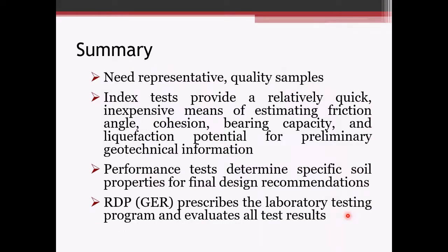So to summarize, we want to make sure we get representative quality samples from the field to the laboratory. Index tests provide a relatively quick, inexpensive means of estimating soil parameters such as friction angle, cohesion, bearing capacity, and liquefaction potential. Performance tests are used to determine the specific soil properties for final design recommendations. And the RDP, which is typically going to be the geotech engineer of record, prescribes the laboratory testing and is going to evaluate the test results.